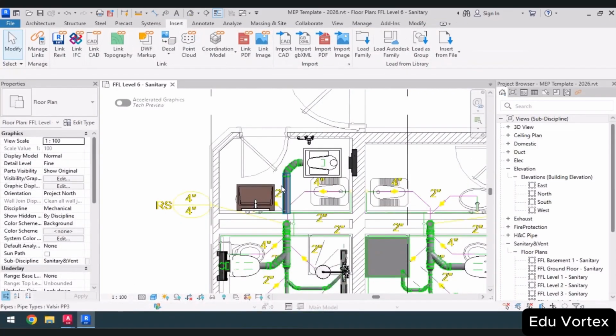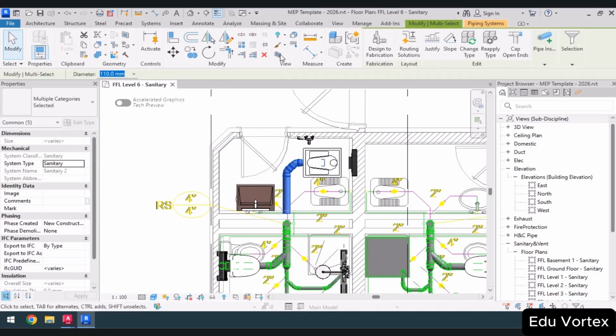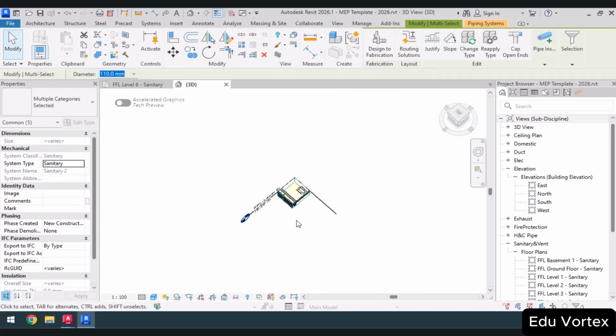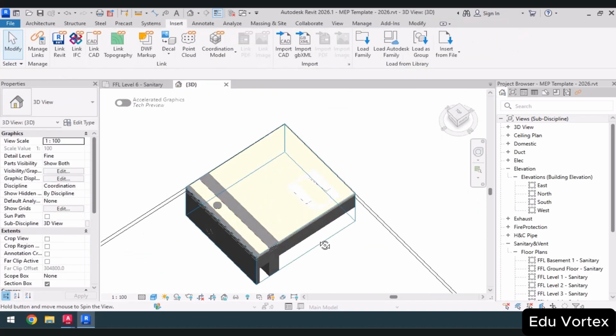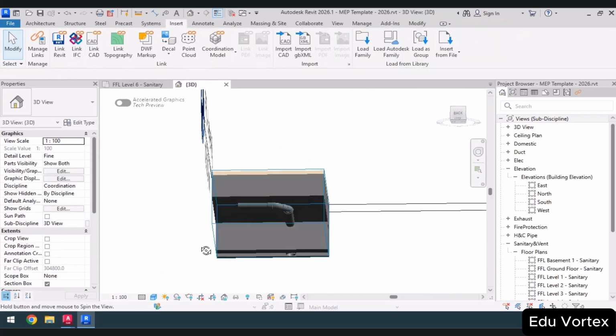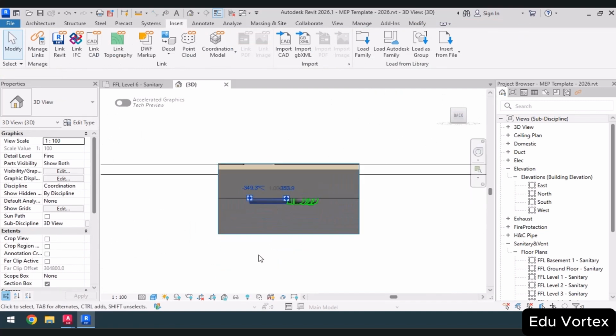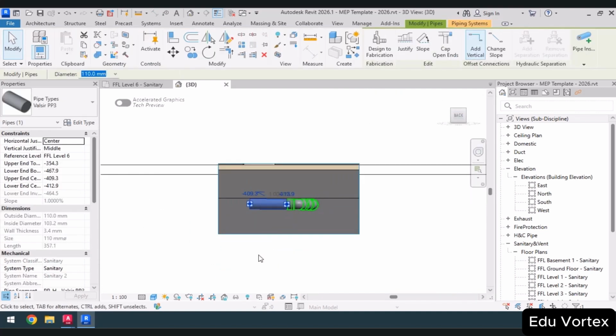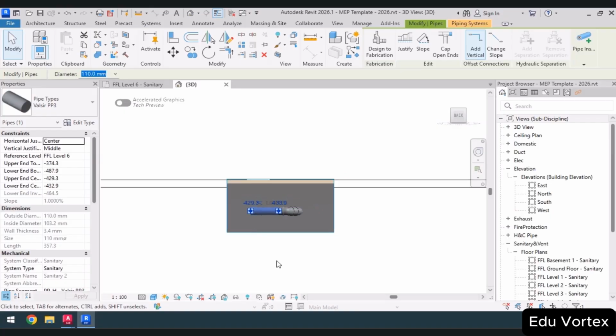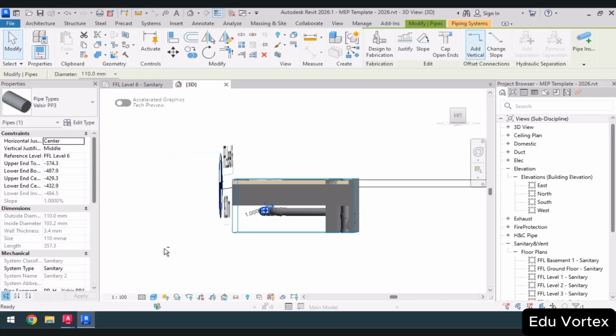So next, let's adjust our height. I can select this piece of pipe and use the selection box option in the 3D space. Currently, it is colliding with the beams in the structural floor, so we will lower it slightly to place it in a suitable position.